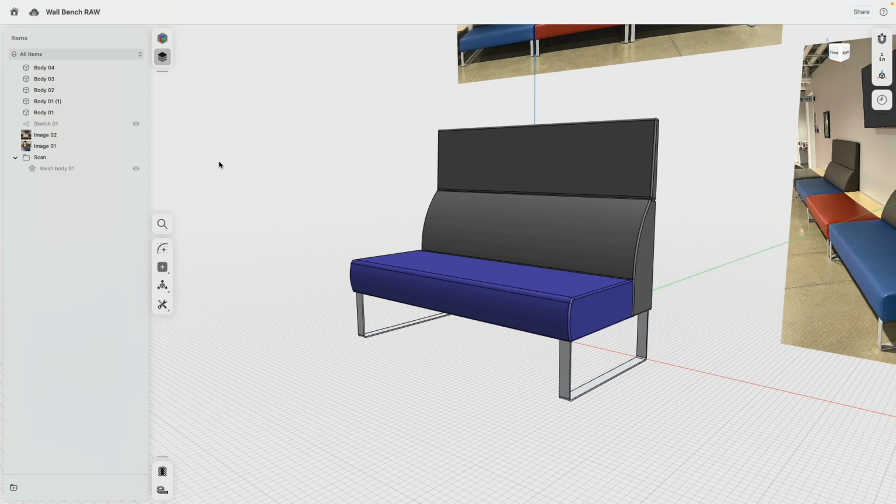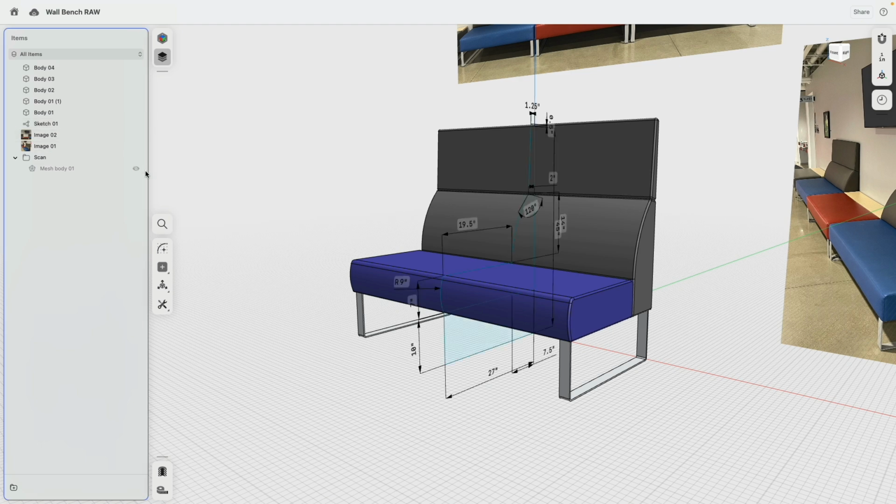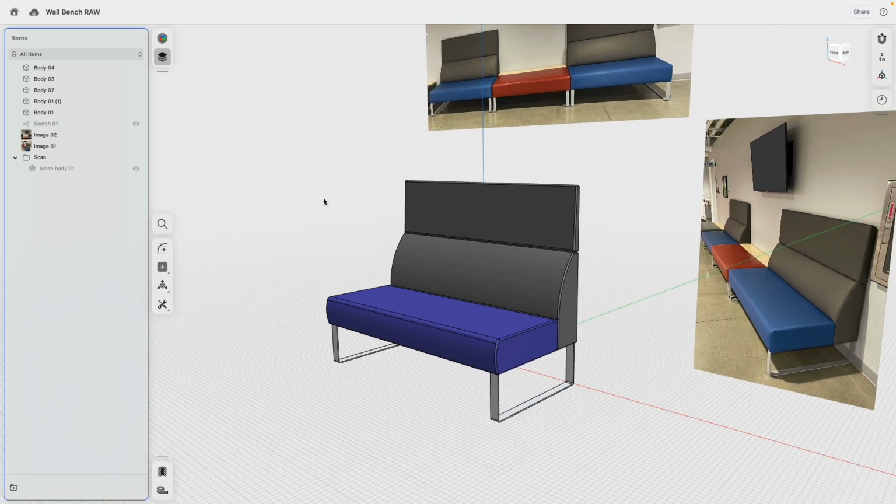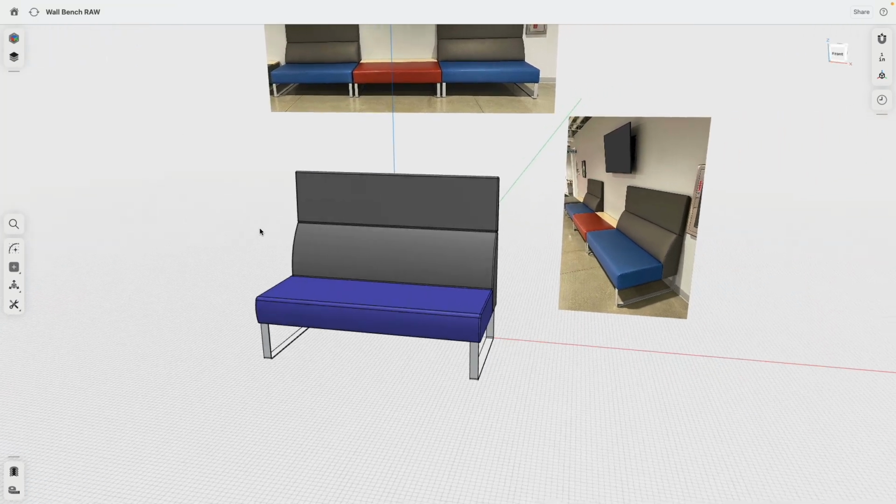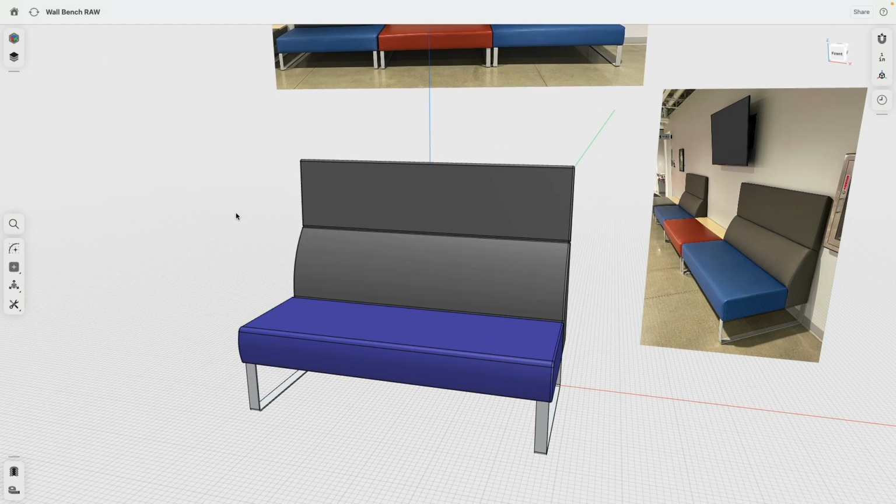So this was a very simplistic model. Now to review, we went into a side view with the scan. Then we built all the basic building blocks, added all the dimensions to it. And then we extruded everything out and finished it then with the fillets, which is a pretty common process. So the fillets you always want to do kind of like really at the end. They can be slow to calculate. The more fillets you have, the more work it is. It's math. And that's the reason why ideally we always do those at the end. Very good. Perfect. That's it.